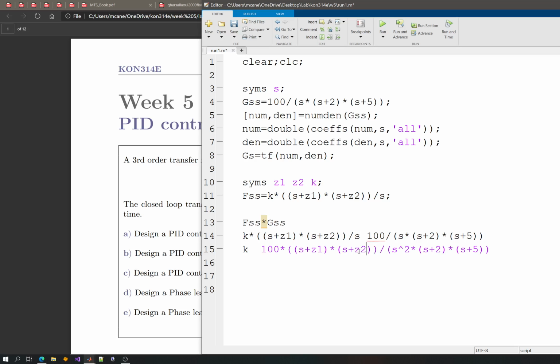If I know the values of these zeros, basically I'm trying to design a P-type controller for a different system. And I've mentioned that if some design point or desired point is not on the root locus, and you're insisting on that design, it might be possible to add some zeros and poles to manipulate that root locus.